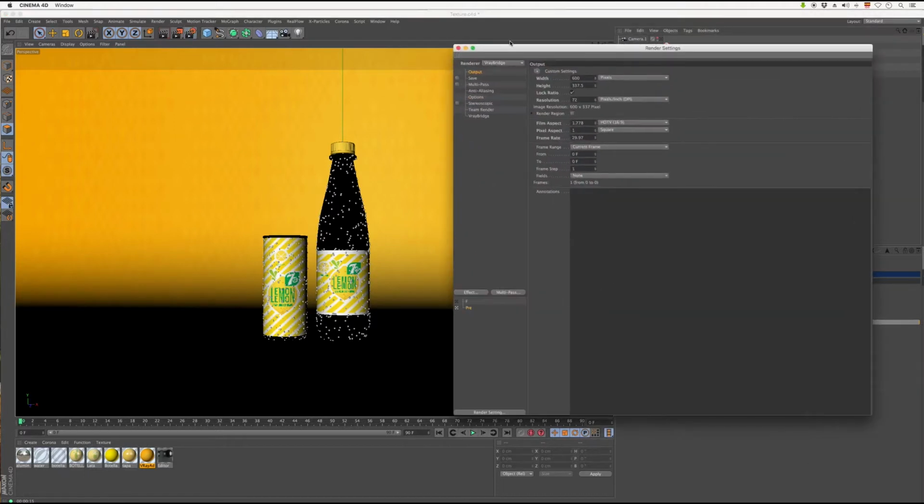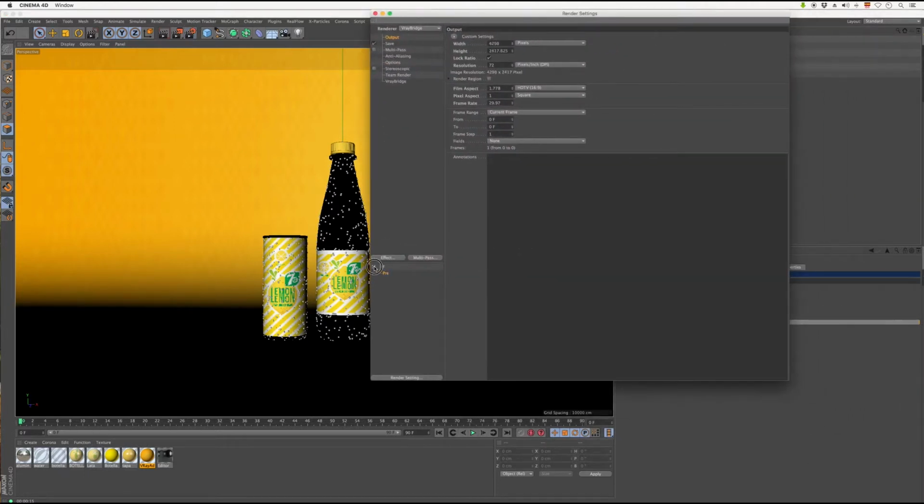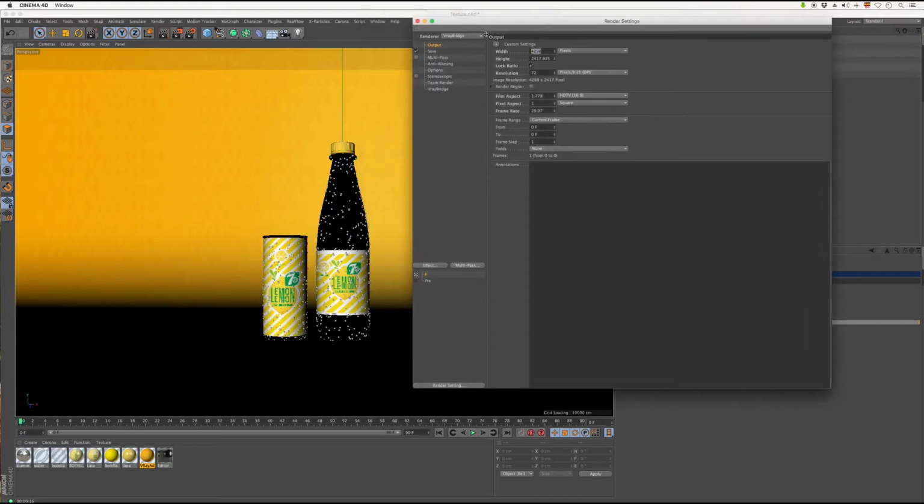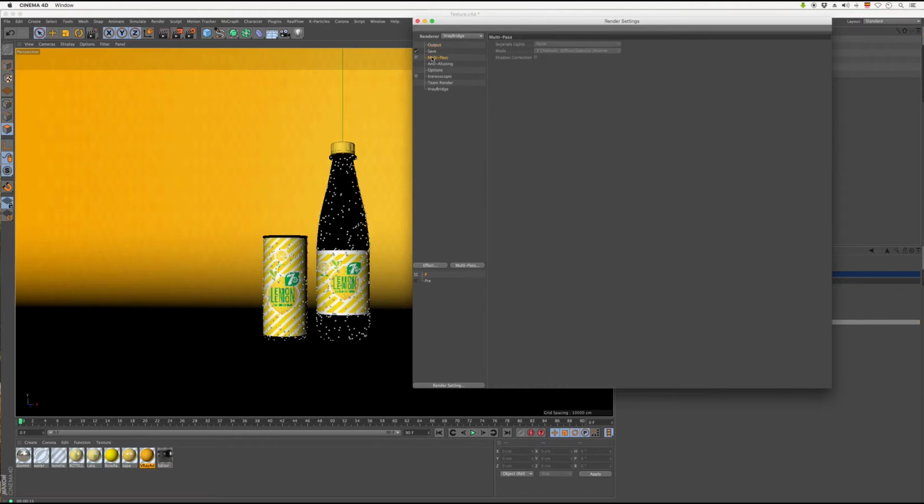The next step is to render our image. So we'll go here and choose the settings for our final render. In output, we'll set the size, so we can put 1920 by 1080. We don't need to adjust anything here to do with the frames. If we wanted to print the image, then we'd need to change the resolution to 300 pixels per inch, but as this is digital, we can leave it at 72.